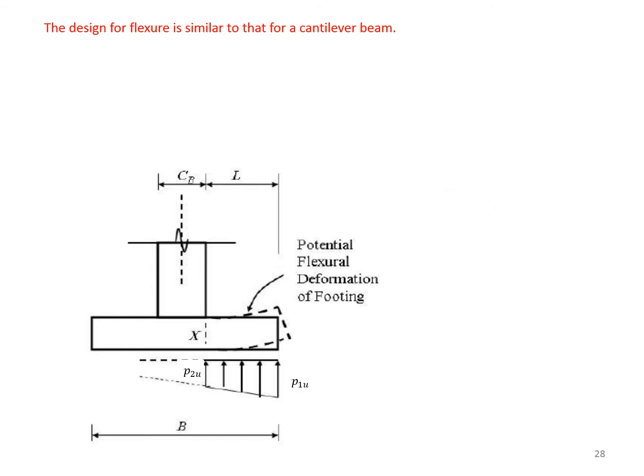The design of flexure is similar to that of a cantilever beam. In a way, if you look at this illustration, you notice that because of this pressure, which is trapezoidal, the footing is bent upward. Therefore, we need to design reinforcement at the bottom, like this. And in the perpendicular direction, of course, we would put the same amount of reinforcement because we always design this for the maximum bending moment. If the bending in the other direction is smaller, we can use the same reinforcement conservatively.